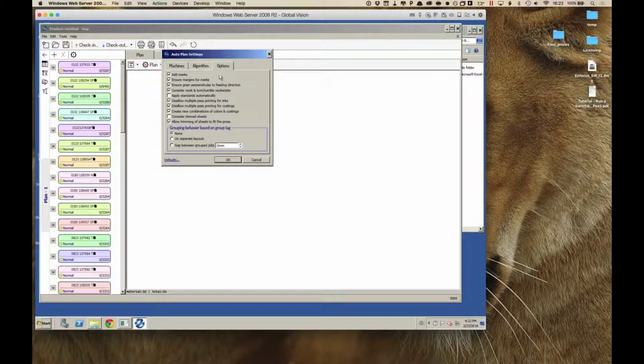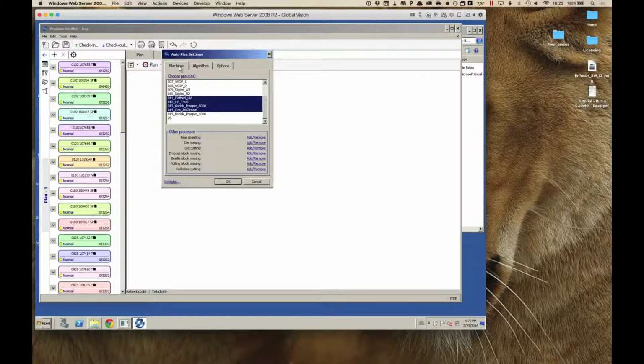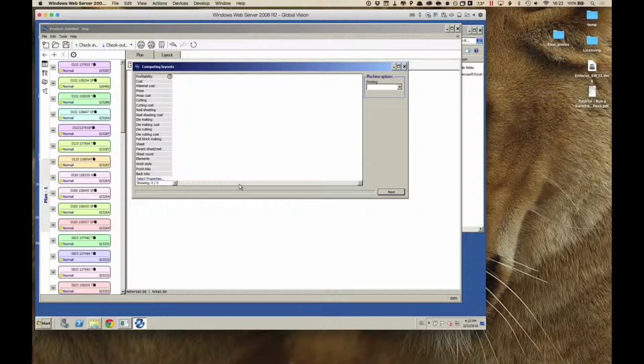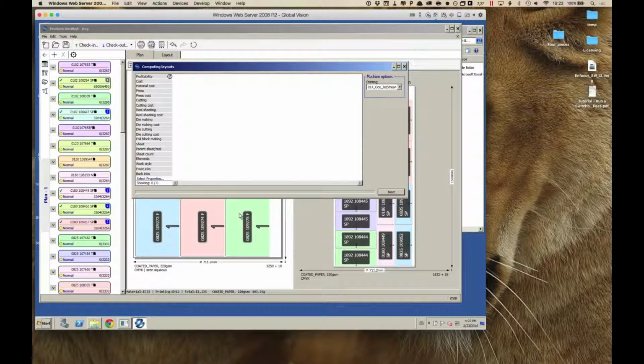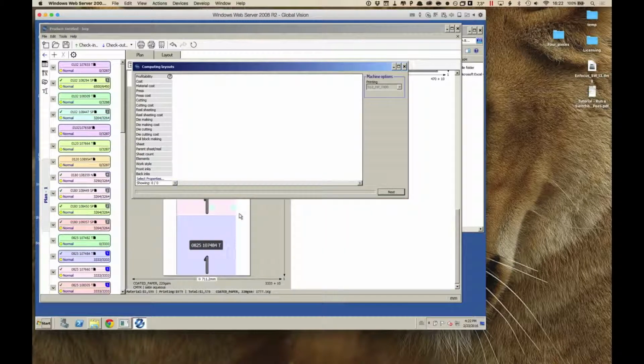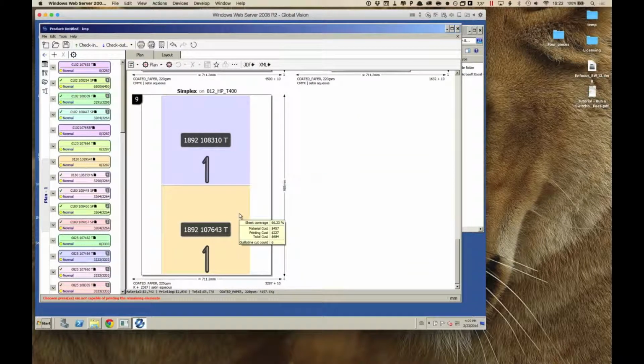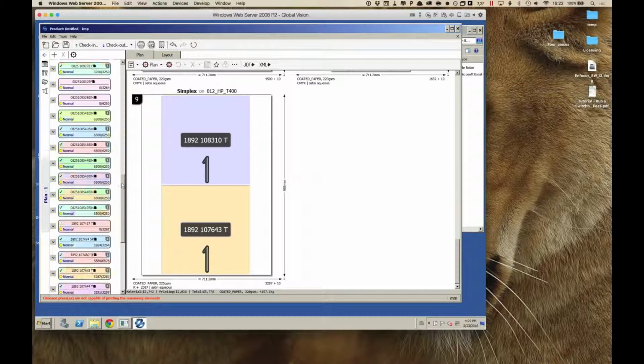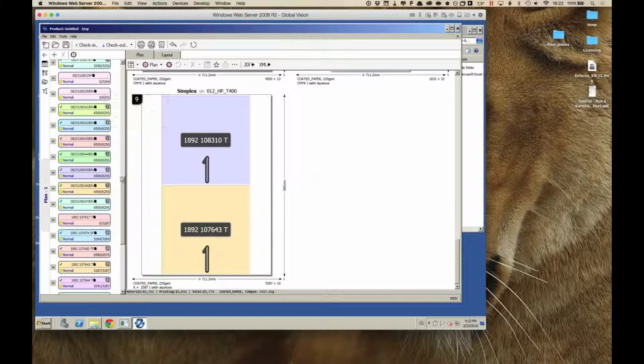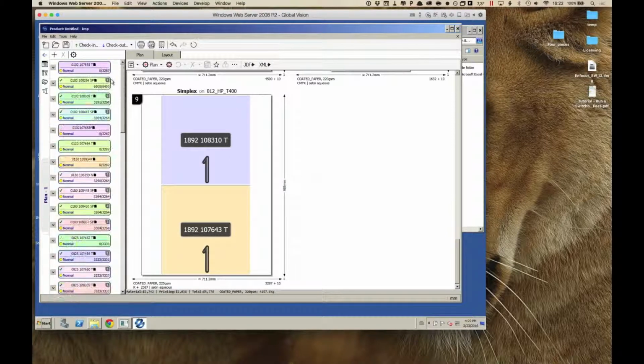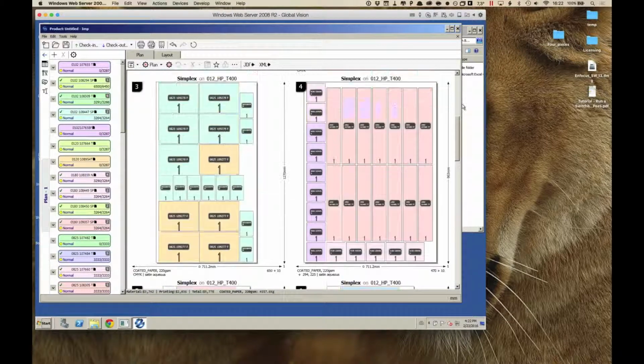And then some additional options, things such as grain direction and so on. So all of those can be set up. They can be made to default as well if you always have the same options. And then I can say plan, and this will take a few seconds because IMP is now going to make sure that all of these components are planned in. On the left-hand side, you can already see where those components are planned. You see these gray numbers that appeared everywhere, and that's the number of the sheet that those components or the layout that those components were planned on.